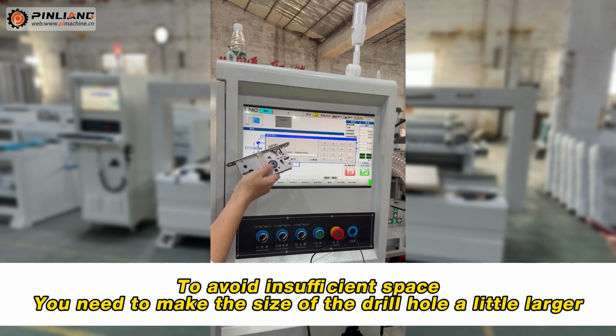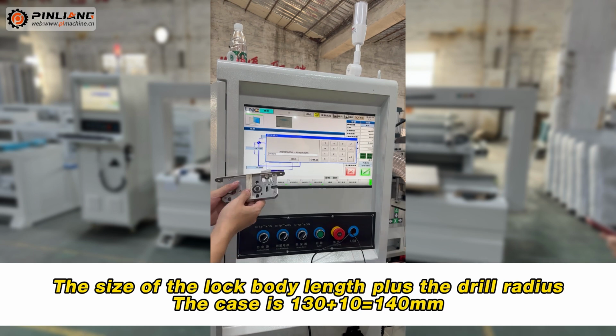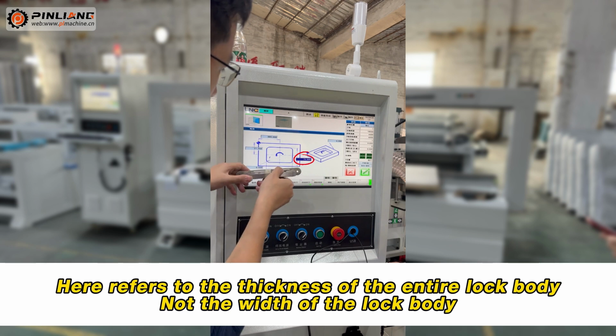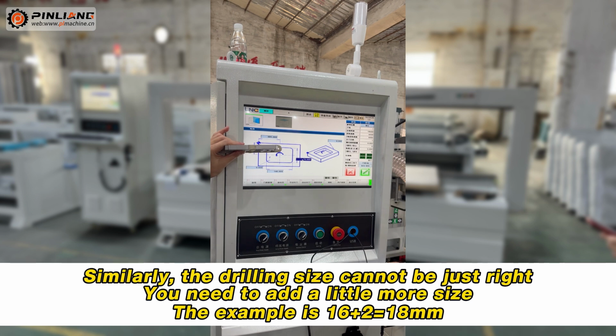To avoid insufficient space, you need to make the size of the drill hole a little larger. Add an extra drill radius. The size of the lock body length plus the drill radius. Here refers to the thickness of the entire lock body, not the width of the lock body. It is equivalent to the thickness at this position. Similarly, the drilling size cannot be just right. You need to add a little more size.